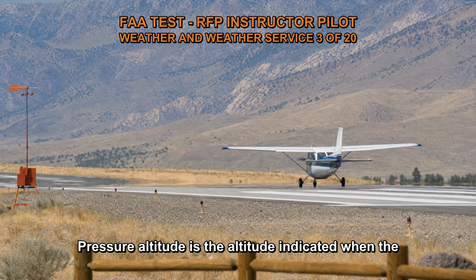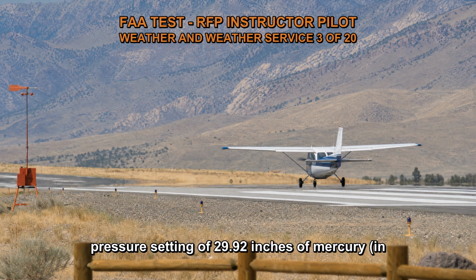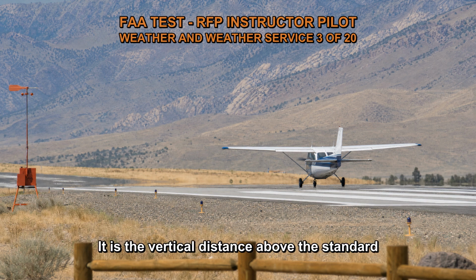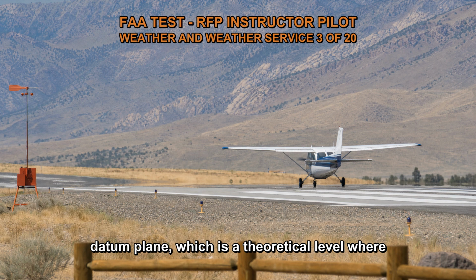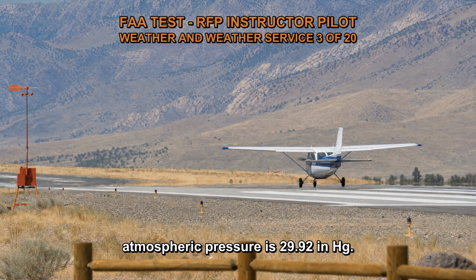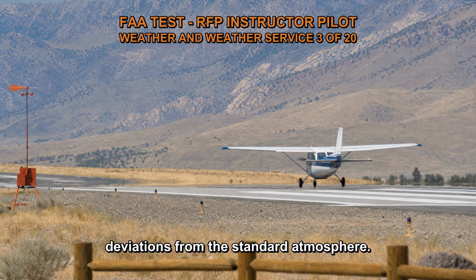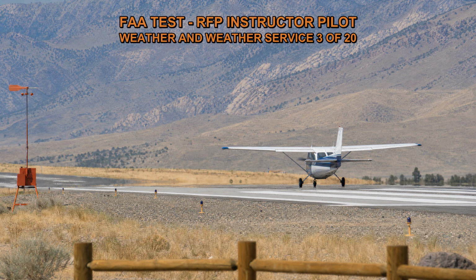Pressure altitude is the altitude indicated when the aircraft altimeter is set to a standard atmospheric pressure setting of 29.92 inches of mercury, in Hg, or 1013.2 millibars, MB. It is the vertical distance above the standard datum plane, which is a theoretical level where atmospheric pressure is 29.92 in Hg. However, in real-world conditions, temperature variations can cause deviations from the standard atmosphere.